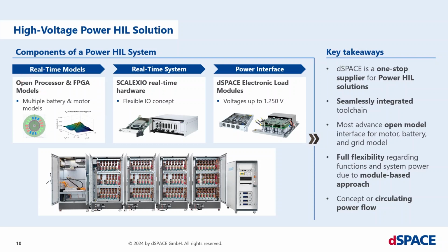So for tasks which have to be calculated very fast, we use the FPGA technology, especially when it comes to machine emulation. We want to emulate also the current ripple, the triangular waveform, which is forced by the switching operation of power electronics devices. So for that, we use the very, very high dynamic FPGA technology.